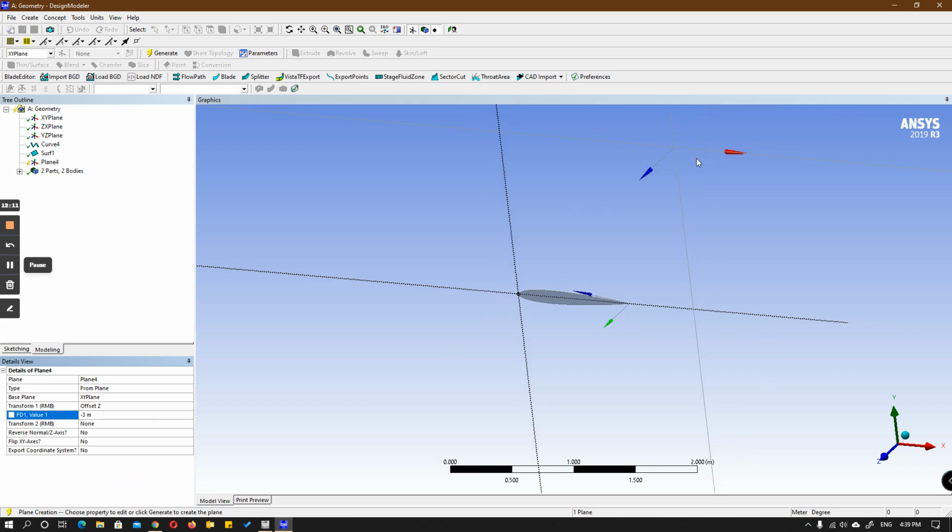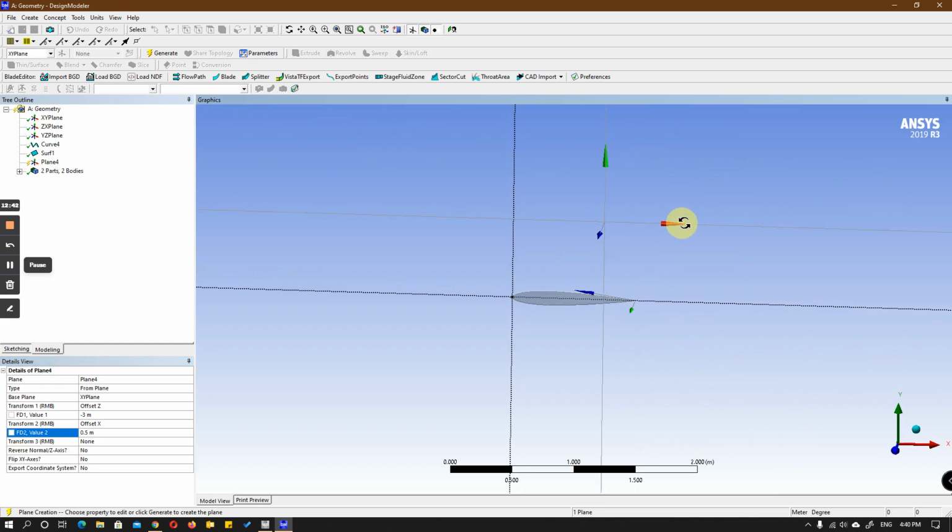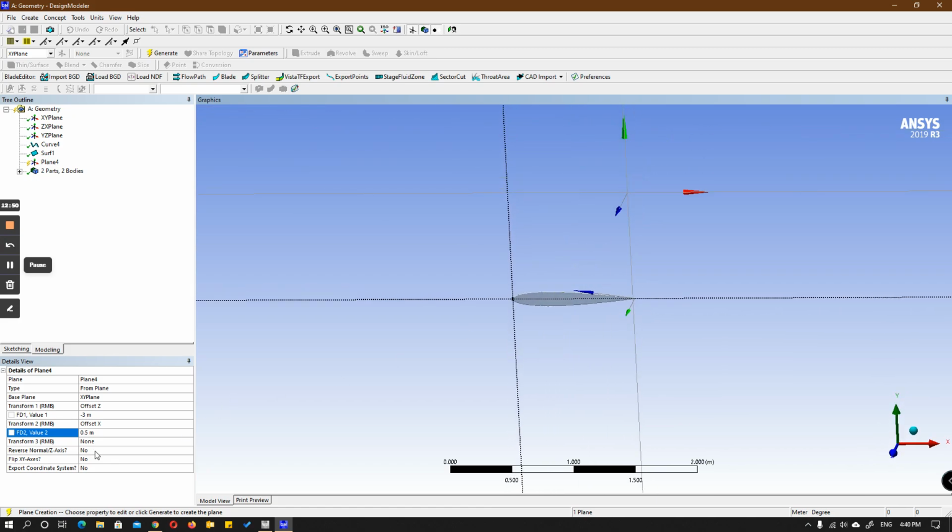Now we can see a preview here, and what we are going to do is transform. The transform is basically whatever we have here, we can change it. So offset X by 0.5. Now you see what happened. What we are doing is offsetting this new plane at a length of 3 meters away from this older plane, and also in this direction. We put the plane like this so we get that tapered direction, right? That offset can be done here itself.